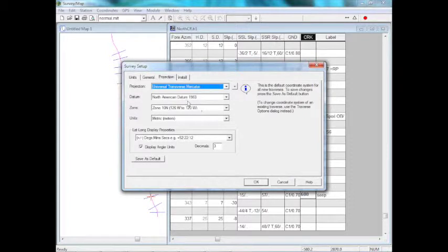So if you're working in UTM coordinates, you can work in UTM coordinates, and then you could convert the data to, in BC, people use Albers equal area projection. You can convert between the two if you need to. Often people work in simply undefined, meaning we don't care what projection we're using. We're just using a consistent coordinate system where everything ties to everything else.